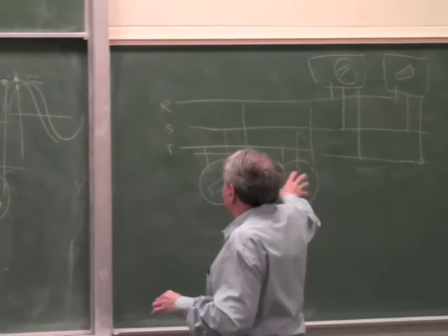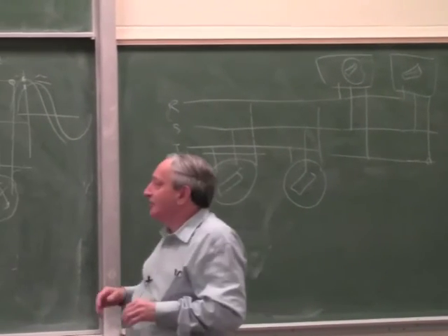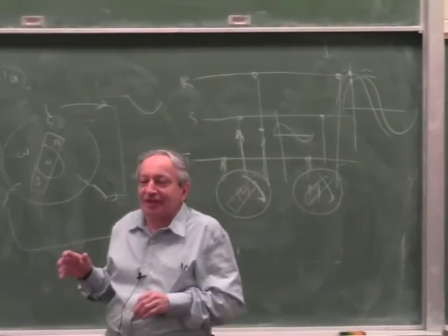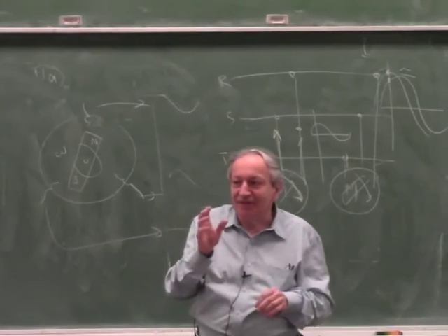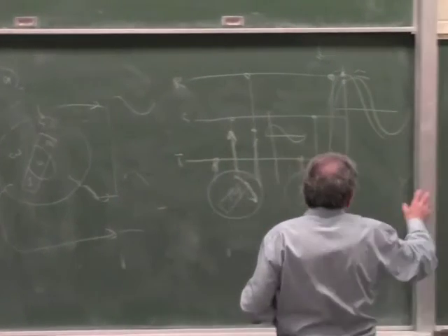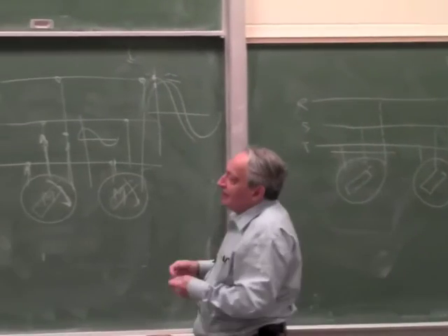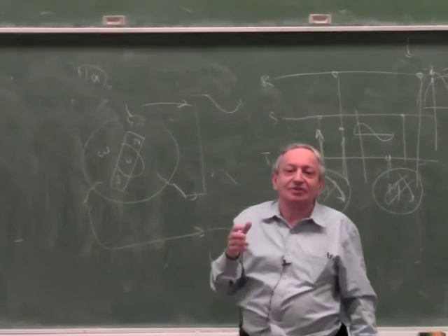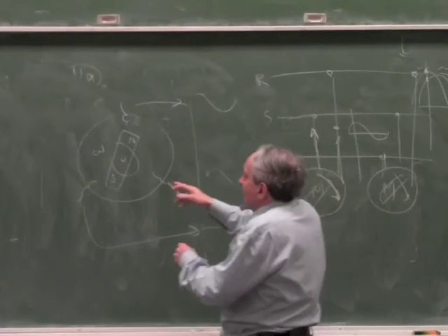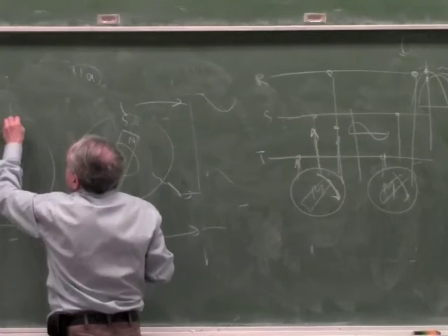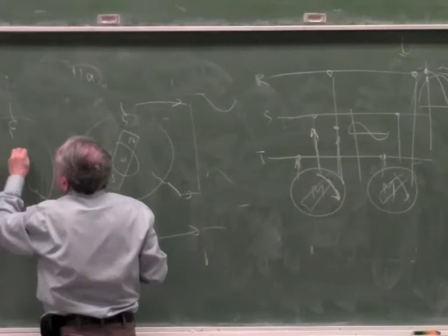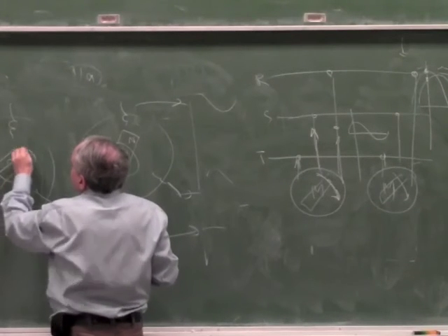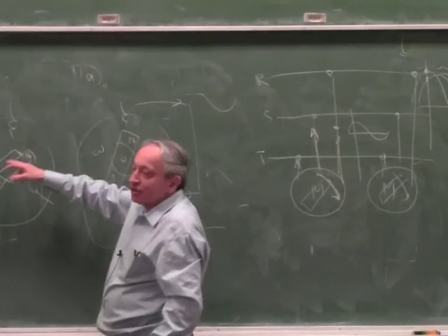So in big systems, this whole regenerative braking is a bit different thinking. Now the last thing I want to raise is how do you do regenerative braking in an induction motor? Because that's actually very tricky. An induction motor is not phased to a grid, but on the other hand, an induction motor doesn't have magnets. So remember, the induction motor works because the armature, which is shorted, is always lagging behind the grid. The induction motor has an armature which just has a shorted coil, so it creates induced poles by induction.